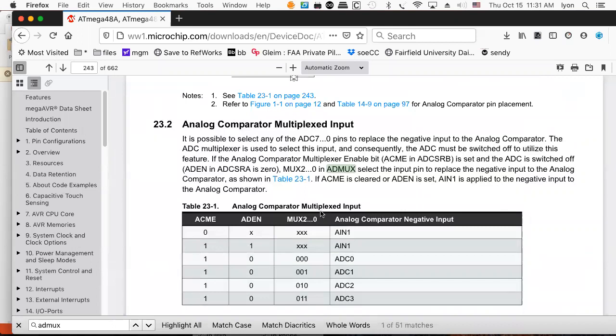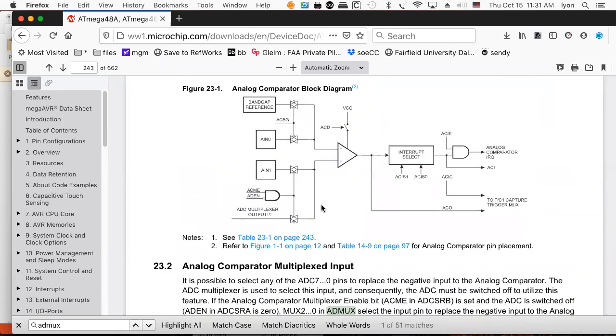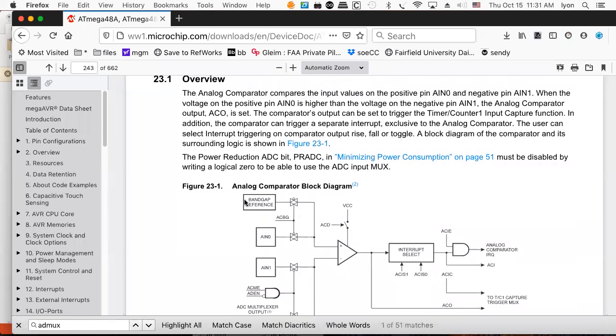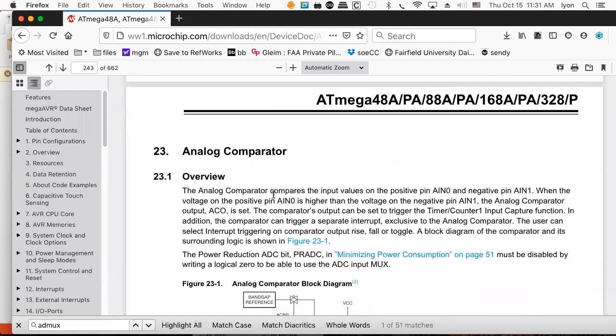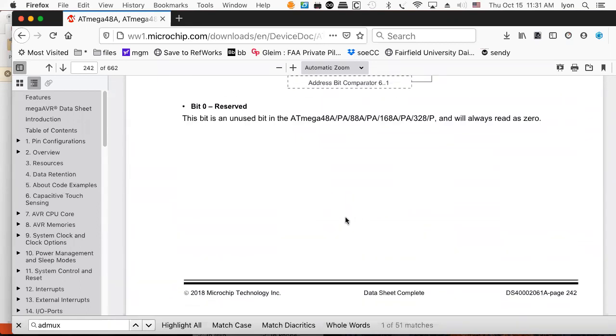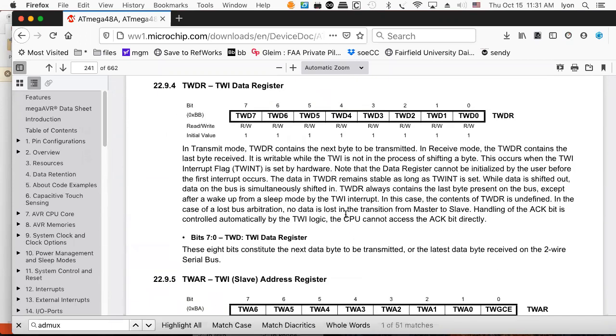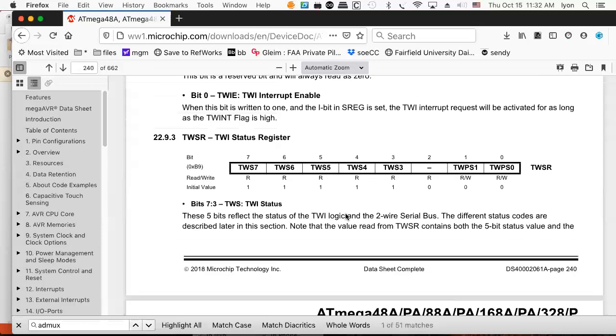If you really want to learn how to use a chip and learn how to program it properly, you've got to read the data sheet. And here's some interesting stuff, this is detail about the band gap reference that they have. And these little guys in here are analog switches that let you take a band gap reference and use that relative to an analog input and do a comparator. And there's all kinds of interesting stuff we can do to talk about analog comparators and how that can be used to trigger our ADC converter input. So that's the data sheet. It's there for you to read.